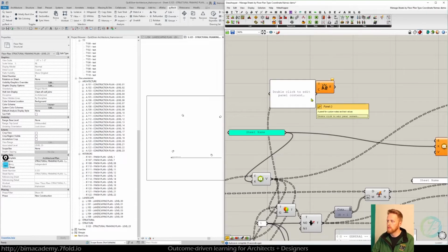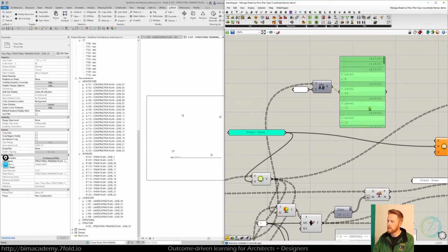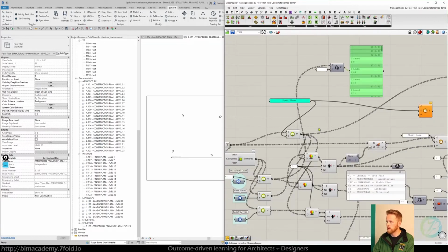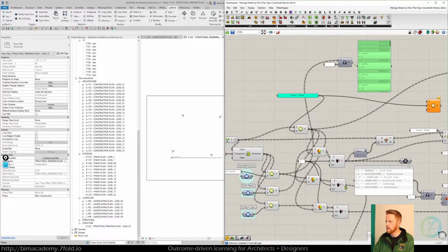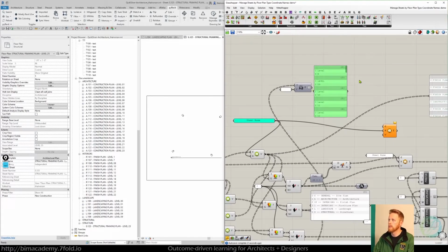So I'm going to just do quotes, double click in and hit the space bar just to create an empty space there, and then feed that empty space into the character break. And then when I check the output, that's going to give me everything I want right there. And actually, I should be doing it through my pruned list. There we go. And I'm just going to right click and simplify that to keep things clean.